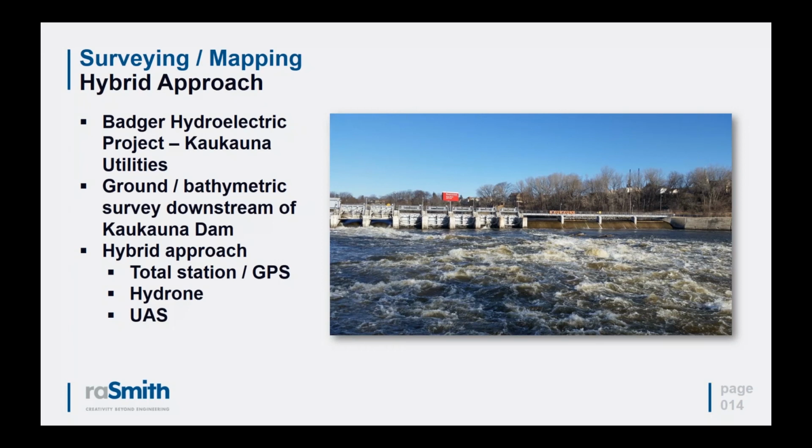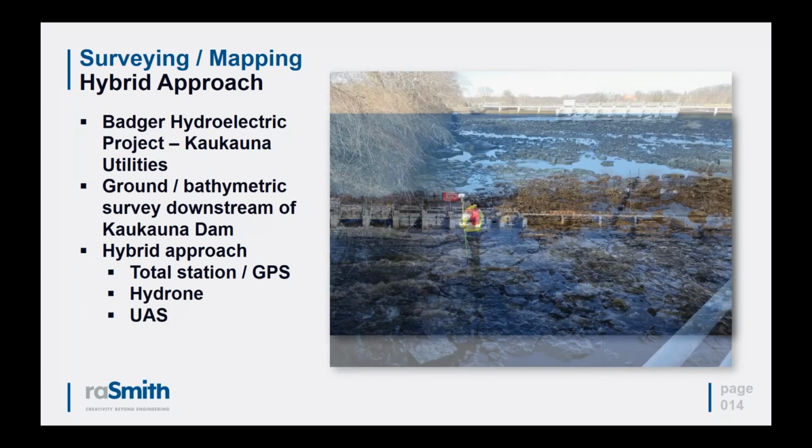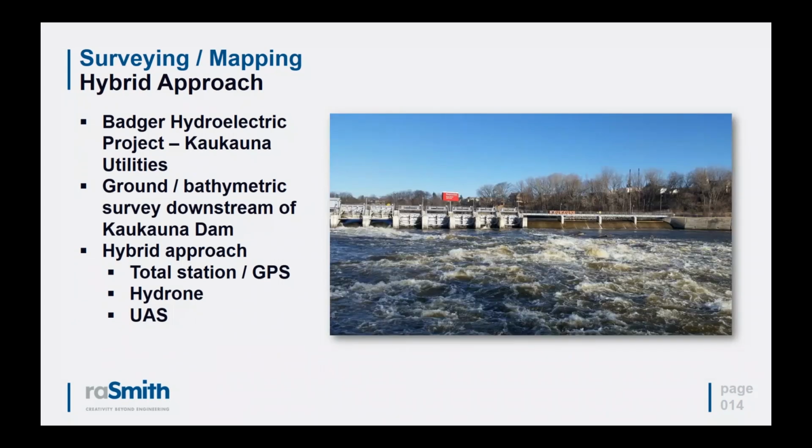We employed a series of different technologies on this project, including a UAS, the Altus LRX, which we saw earlier, but we also used total station and GPS, and a Hydrone in this particular case, which is a different type of drone, a water-based drone, which helps us using sonar map surfaces beneath water. It's kind of compelling, and I have a couple more images here.